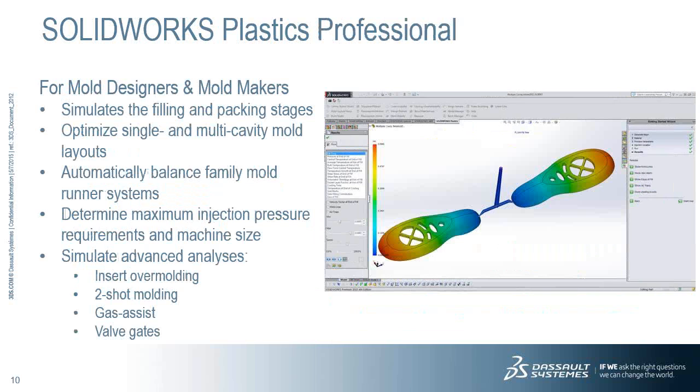Plastics Professional comes with a little more added value. It is targeted at mold designers and mold makers, and goes a bit deeper into the process, allowing users to simulate both the filling and packing stages. Standard helps me see the filling stage, but in Professional, it also helps me with the filling and packing stages of the injection molding process. You can analyze and optimize single cavity, multi cavity, and family mold layouts. Automatically balance your runner systems if you are running multi cavity molds, and determine maximum injection pressure requirements and molding machine size,